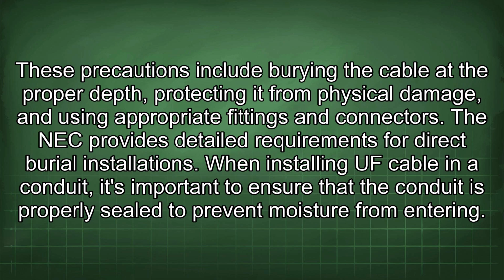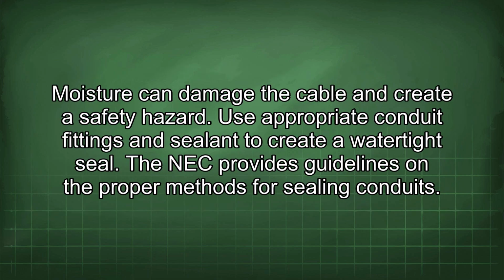When installing UF cable in a conduit, it's important to ensure that the conduit is properly sealed to prevent moisture from entering. Moisture can damage the cable and create a safety hazard. Use appropriate conduit fittings and sealant to create a watertight seal. The NEC provides guidelines and the proper methods for sealing conduits.